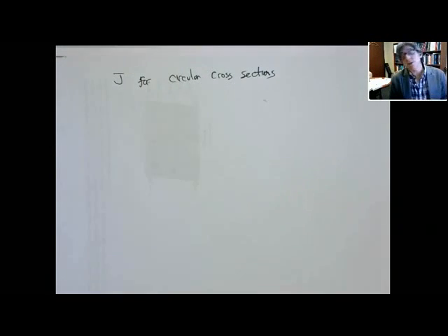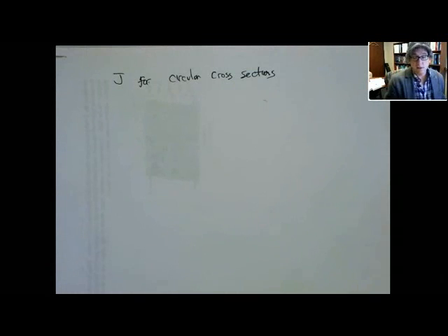We probably won't get to it too much in this class, but really, this theory is only valid for circular cross sections. Even when we use it for hollow circular cross sections, it is a bit of a simplification. As you get to very thin circular cross sections, where the outer wall is a very thin-walled tube, all this theory we've done with Tc on J actually starts to break down.